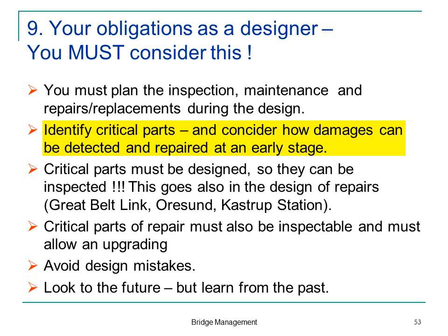But if you design a bridge when you're graduating, then please consider prior inspection, maintenance, and repairs during the design. It's going to affect it. When you design a bridge or anything else, try to identify the critical parts. Critical parts are those where you know you have the highest risk of deterioration. Critical parts are those where you really know you need all your reinforcement here. You don't want corrosion there. And these critical parts, you must design them so they can actually be inspected.